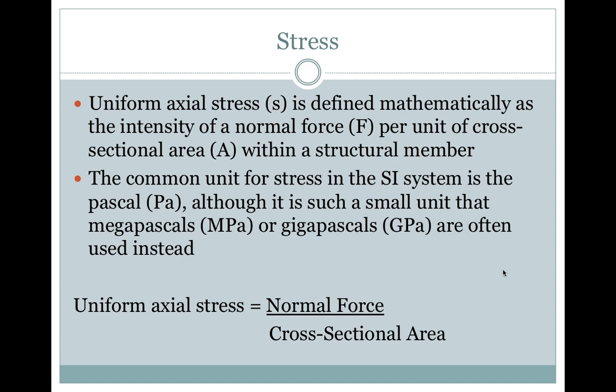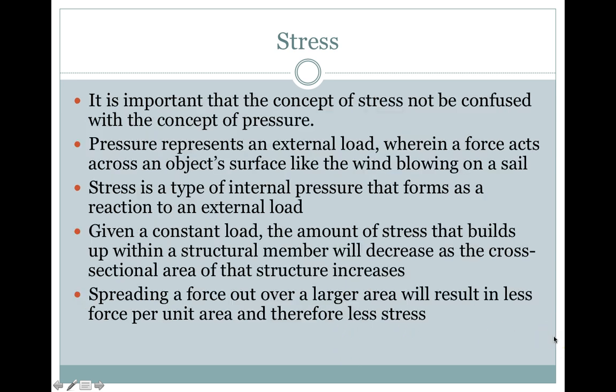The common unit for stress in the SI system is the Pascal, although it is such a small unit that megapascals or gigapascals are often used instead. So the formula is uniform axial stress equals the normal force divided by the cross-sectional area.